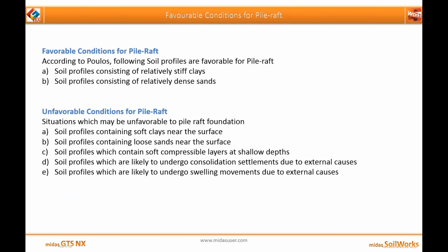Now, what are the favorable conditions for pile raft? According to Poulos, the following soil profiles are favorable for pile raft foundation: where the soil profile consists of relatively stiff clays, or soil profiles consisting of relatively dense sand.